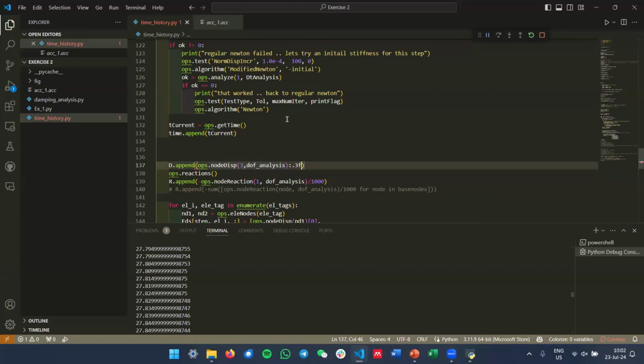You can do it, but it's a matter of Python in that case. If you're using the standard recorder of OpenSees, right inside the file you can declare a parameter called precision, if I remember correctly. It's dash precision, and then you give the number of digits after the point.